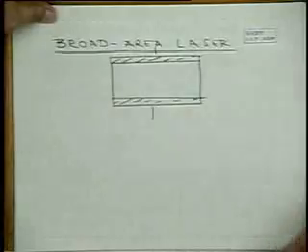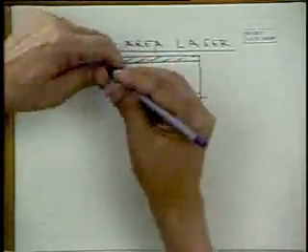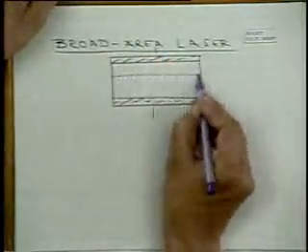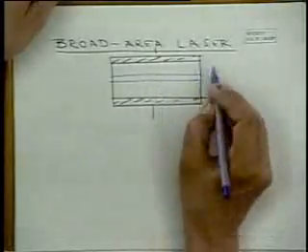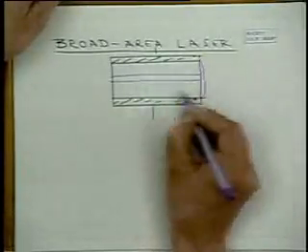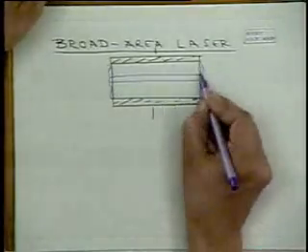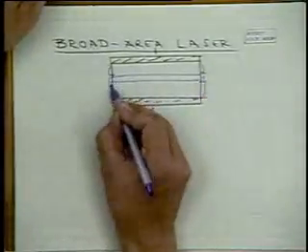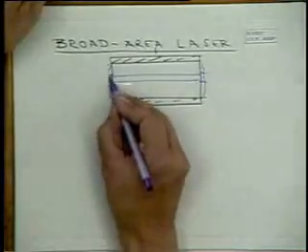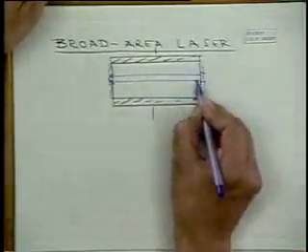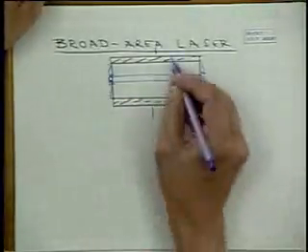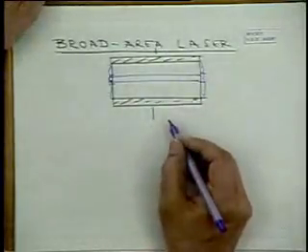What are the disadvantages? Obviously there's a PN junction here somewhere. So at the PN junction, there may be some leakage current around the periphery. There may be breakdown, additional leakage at the junction of high electric field. And if you're passing a high current, what may happen?